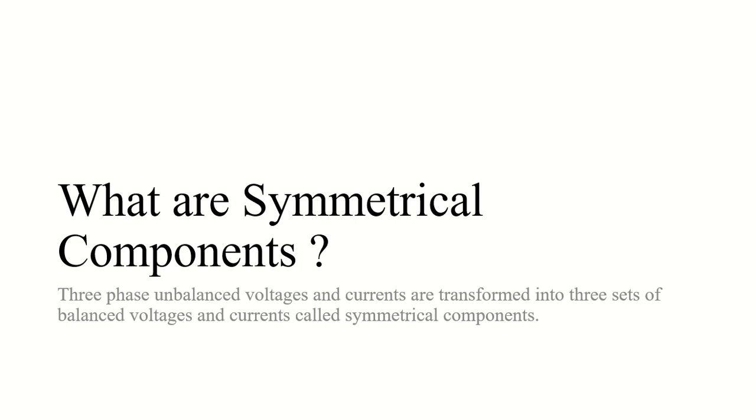So, these are the zero sequence, positive sequence, and negative sequence impedances, and you can find them for anything. You can find them for a transformer, for a generator, for transmission lines. You can find these zero, positive and negative components for anything you like, as long as it is an electrical system. And these components will simplify the analysis of unbalanced conditions.